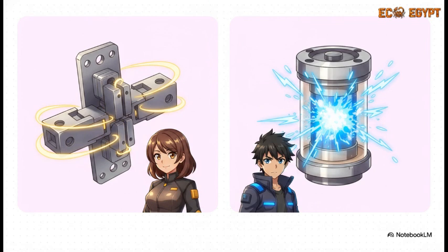The MVCB, on the other hand, that's your emergency brake. It interrupts fault and load currents using a specialized vacuum bottle designed for huge 25 kiloamp fault interruptions. And it actually has an integrated numerical protection relay. So the LBS handles daily traffic, while the MVCB stops the catastrophic crashes.